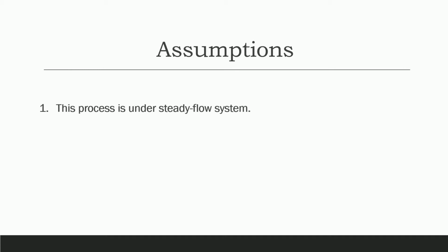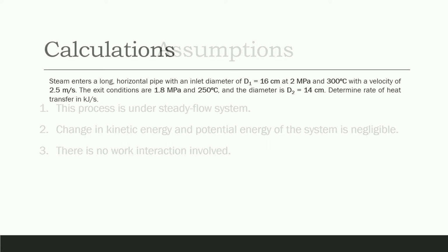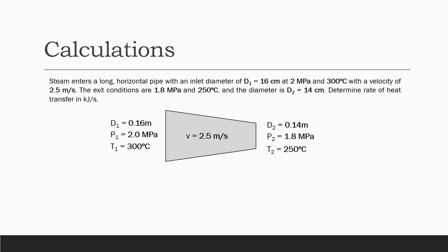Number 1, this process is under steady flow system. Number 2, change in kinetic energy and potential energy of the system is negligible. Number 3, there is no work interaction involved. Now we can start with the calculations.